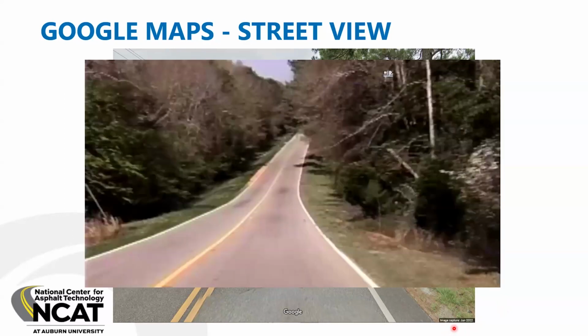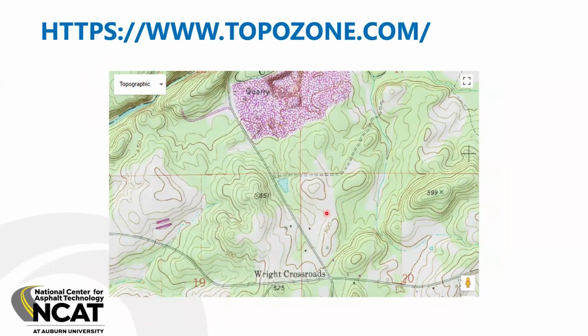And then there's little things that you can get that non-pavement people might not even see. So those of us that actually look down at the road when we're driving down the road may pick up that there's some dark spots down here. So these are possibly oil spills, something going on the road from these vehicles. And what could be causing that is an area of localized roughness where the vehicles are basically shaking when they hit that spot and shaking some of that oil loose. Or it could just be that that is starting to fail, and that is what's causing that roughness. So again, you never know where the piece of information is going to come from that's going to be useful. So always be open-minded to where you're getting it from.